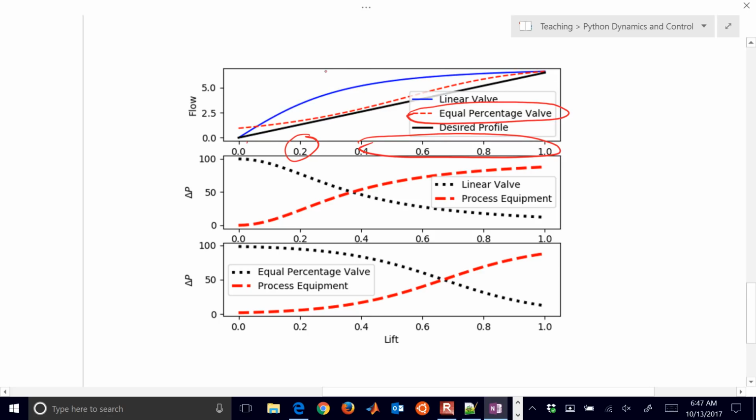So you have kind of two slopes here, a very rapid rise at the beginning, and then it becomes very insensitive at the end. So this is not desirable, because when we're designing a control system, we'll have different gains in different regions. And so the equal percentage valve is going to maybe perform better for our control system, because then we know that a certain fraction of opening on the lift is going to lead to a certain constant fraction of increased or decreased flow.